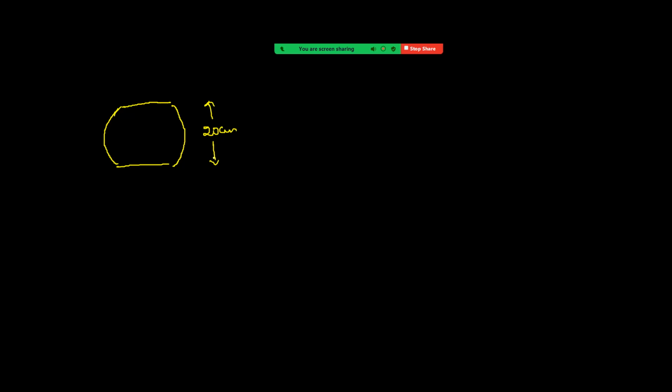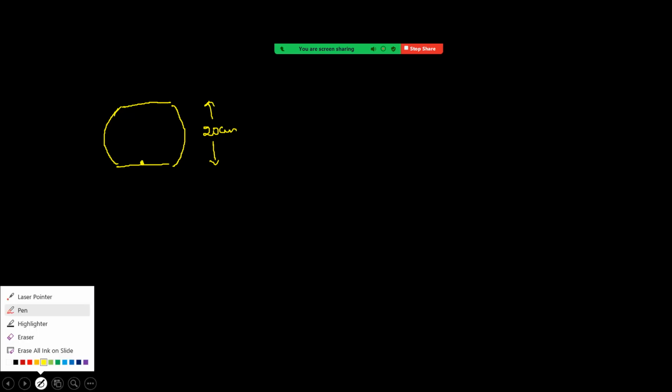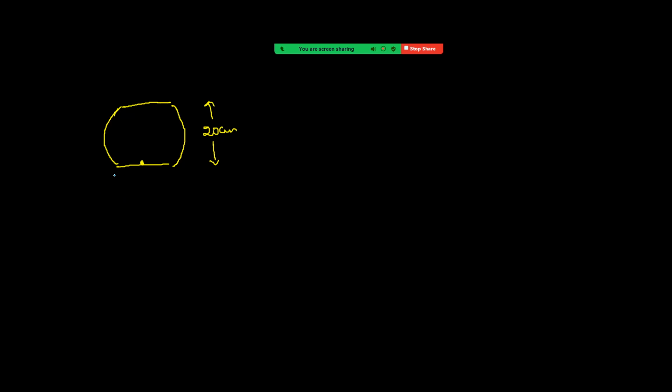Right, the first one, force exerted by water at the bottom. So at the bottom, we have to find the force by liquid. In that, first we have to focus on what is the pressure at that point. Pressure at that point equals pressure of atmosphere, that is P naught, plus, now this depth equals H. So the pressure at the bottom, I'm taking suffix B for bottom, is equal to P naught plus H rho g.